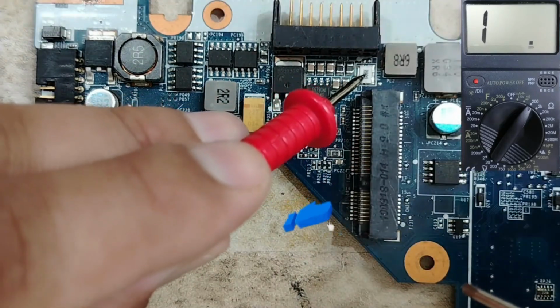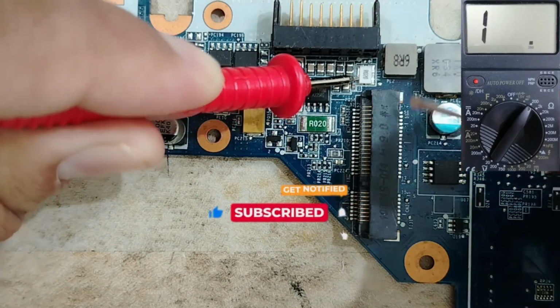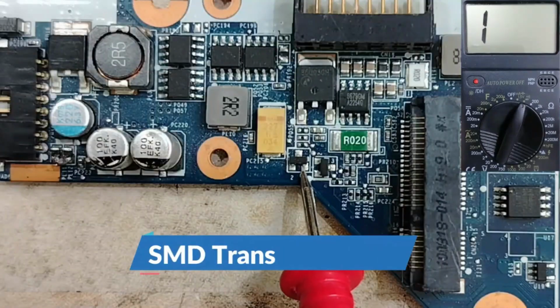Here we have another current sense resistor. If we check it, about the same value, 1 ohm, 1.1, let's check. We have 1.1, 1 ohm, 0.9. So this is good. The dot means what?